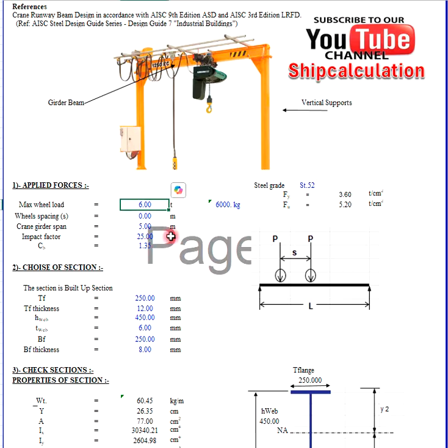And I can see here the crane girder span between the two spots is 5 meter. The impact factor we are using here is 25% from the total force. And then the safety factor we are using here is 1.35. You can change it to make your lifting calculation safe before you do the testing. You might change it to be 2 and maximum is 2.5.